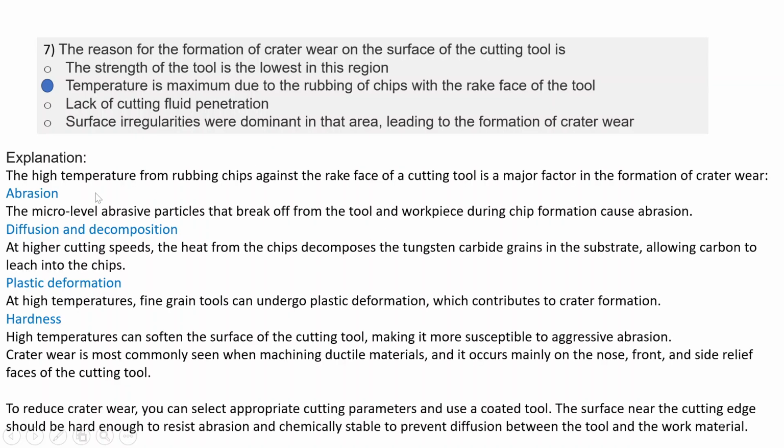The high temperature from rubbing chips against the rake face of a cutting tool is a major factor in the formation of crater wear, and some other factors are abrasion, which is micro-level abrasive particles which break off from the tool and workpiece during chip formation. They cause abrasion.